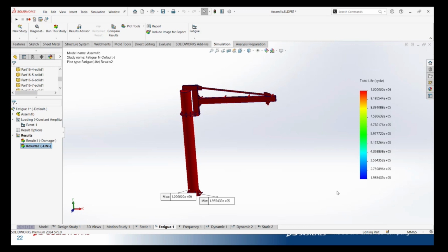So here, fatigue is taken from the results of the static load. Before we carry out the fatigue analysis, we have to do the static load. Static load means it's a one-time application. If the task is repeated, however, the life of the jib crane has to be analyzed with this fatigue analysis.